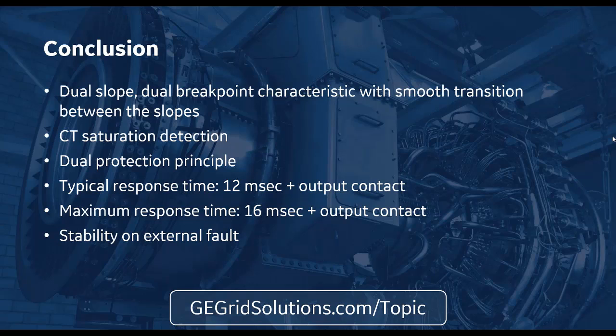You might comment on a good question I'm glad somebody raised, and the question reads the equivalent of, can arc flash protection be used in lieu of bus differential protection, or are the two distinctly different or mutually exclusive? So arc flash protection is there for a specific reason, and that is to reduce any arc flash energy. And that arc flash energy does not necessarily have to come from a bus fault. It can come from a breaker fault too, right? The switchgear fault. It doesn't necessarily have to be in the bus.